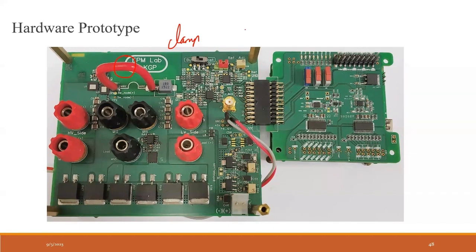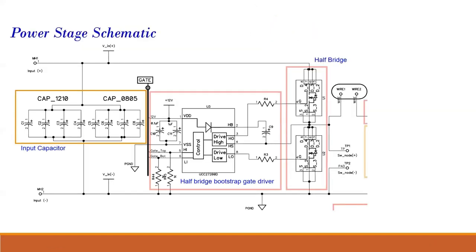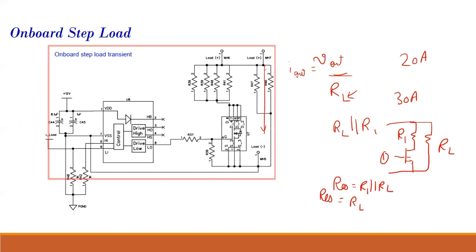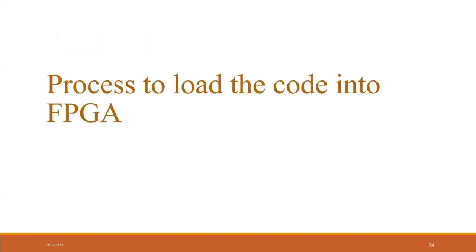So actually, this is my inductor, and this is my switch, all that. This is all inside the PCB, so I cannot put something wire-wrapped. So what we do is we give an external provision of a wire, and I wrap around this. That's how it is done. These are for the voltage sensing and current sensing.